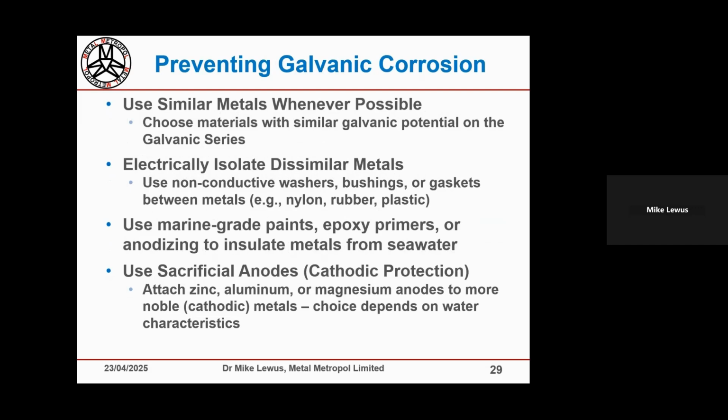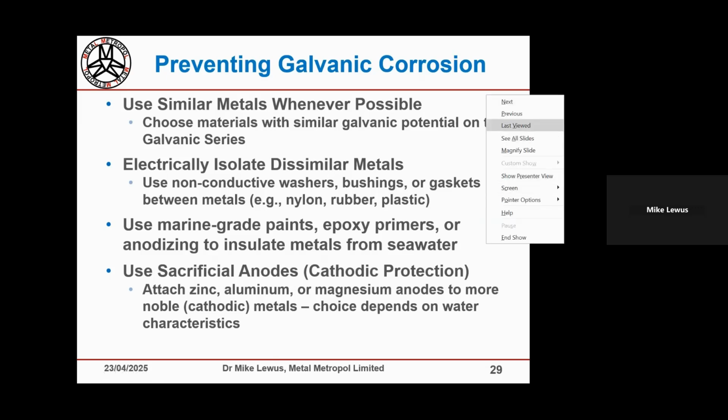Ironically almost, we use our knowledge of galvanic activity to protect the parts we want to protect. So we actually use sacrificial anodes, don't we? Because we know that if we use them in a galvanic couple, it's the anodes that we're going to lose, not the materials we're trying to protect. So just knowing a little bit about galvanic corrosion has got us a long way, because it immediately enables us to have the means to protect the parts we want to protect and be prepared to throw away on a regular basis the parts we're not too bothered about, albeit we do need them, the actual anodes.